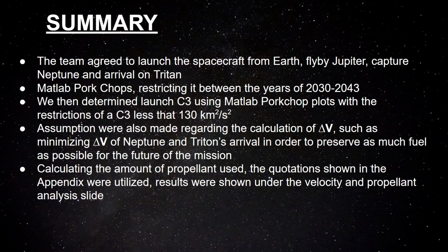So in sum, the team agreed to launch the spacecraft from Earth, perform 1 flyby by Jupiter, and perform a capture at Neptune with an arrival rendezvous at Triton. We used MATLAB pork chops and restricted the launch dates between 2030 to 2043, and we determined our launch C3 using MATLAB pork chops, with the restriction of C3 being less than 130 kilometers squared per second squared.